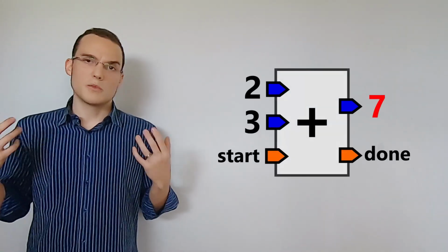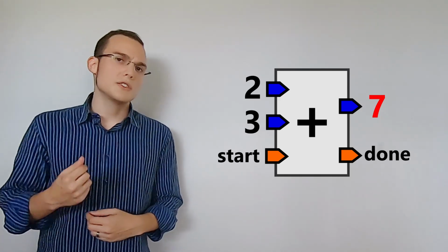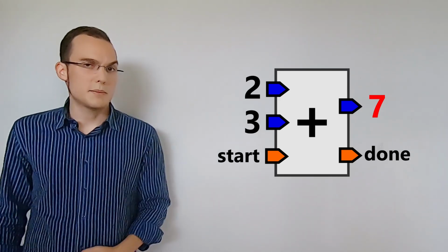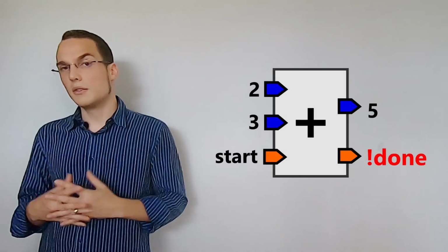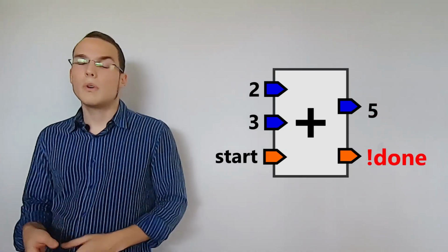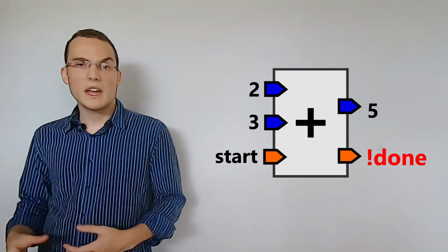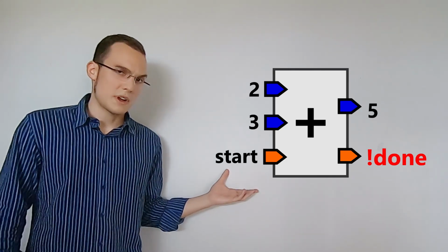This separation also helps with the modularization of your circuit. If you have some kind of computation problem, you already know that you should look at the data path. However, if your circuit is not waiting for some signal, or if it's running while it should be idle, you probably have some problem in the control path. That way, it's much easier to find the problem and to correct it.